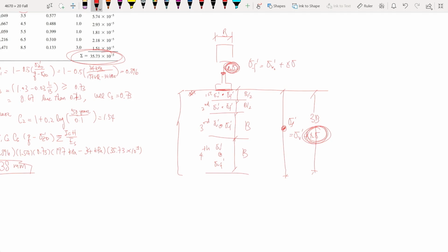And we want to balance between too many layers and just enough layers. And these recommendations from Terzaghi are based on square footings. So that's the approach we use to find the settlements for primary consolidation.